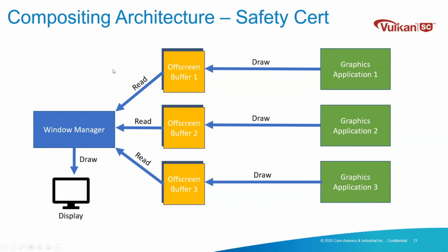The window manager can then access all the frame buffers and display in one go on the display. So what you can do is have a background display that's always fixed. You can have the other displays which can have some transparency and provide objects on top of the main display background. So you can make them transparent so they don't overwrite the background display.